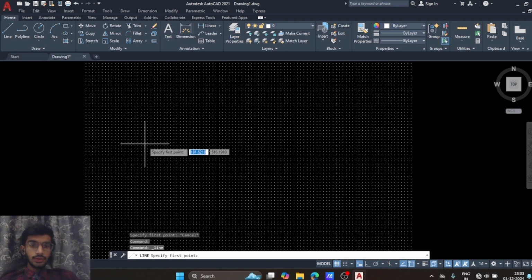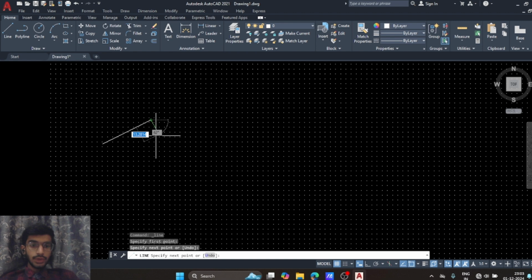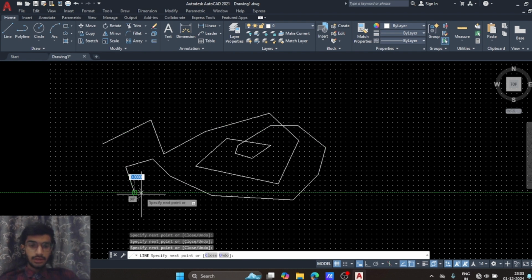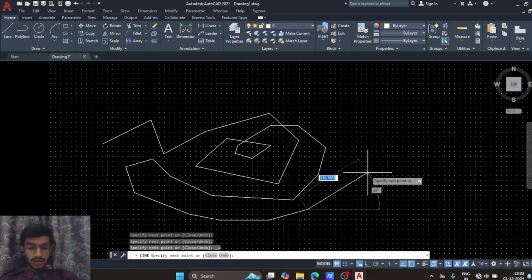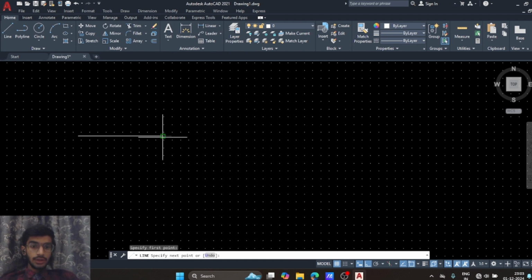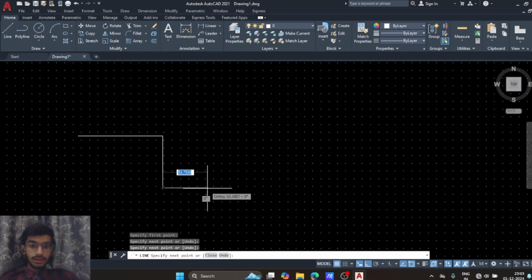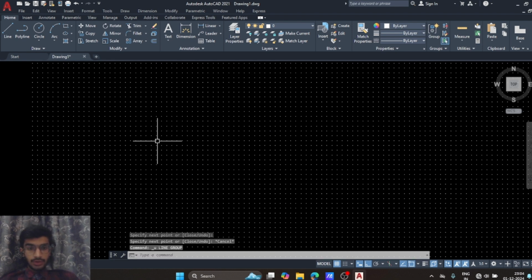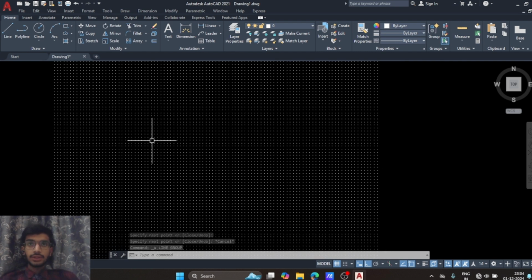So what do we have to do? We can create any line here, but without giving any scale it is not accurate. Here the software gives us a further setting named ortho setting. If we turn this on, we have the correct scale. Suppose we have to draw a line of 100 mm.